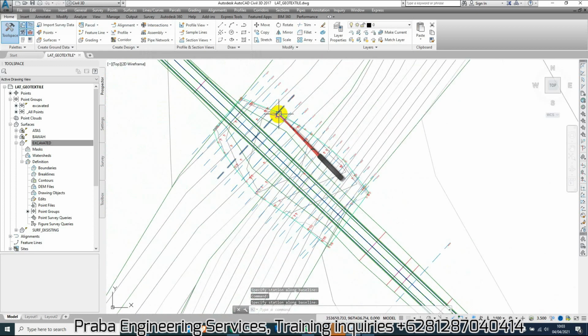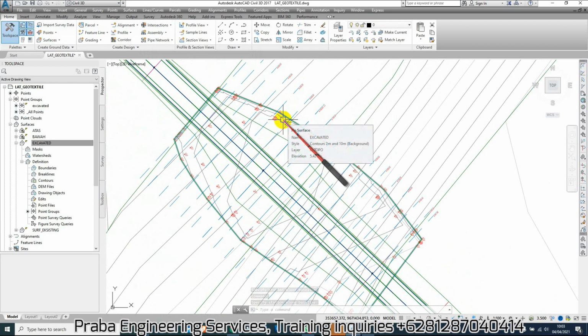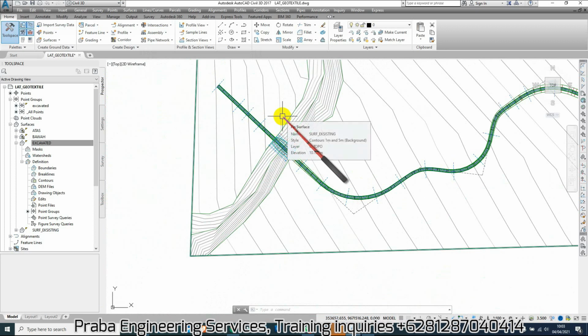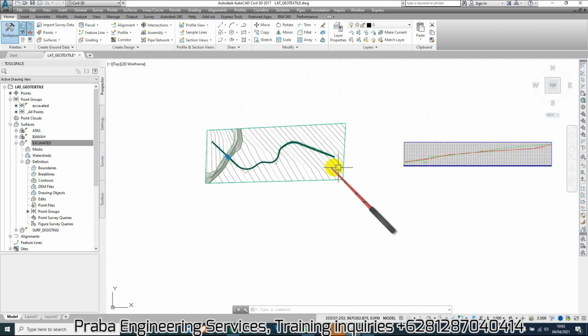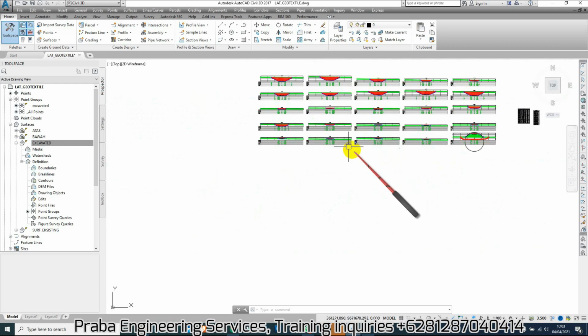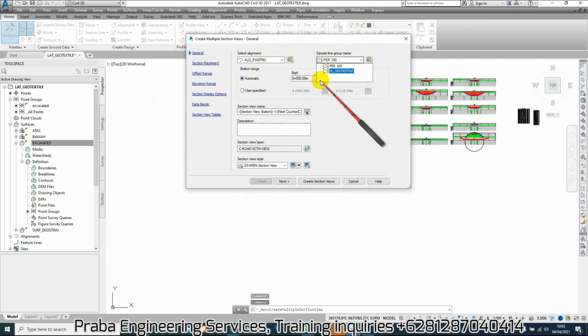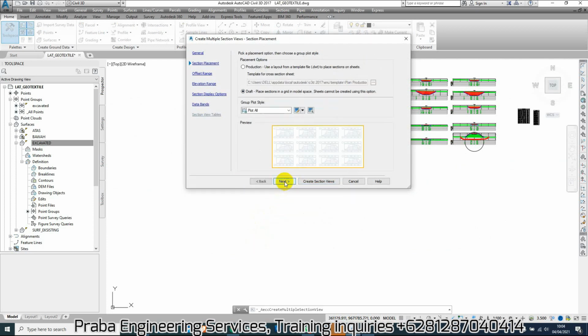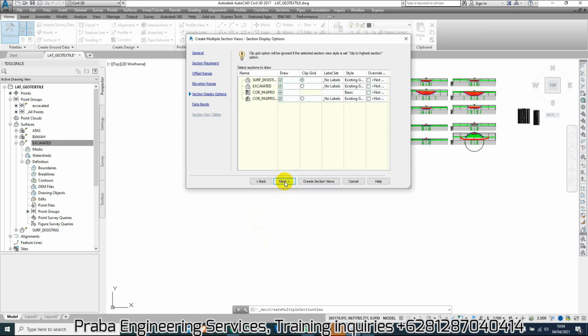Every 5 meters on that location, I already have more detail than the general cross section, because in the general cross section we have only 25 meters. It's very far. Then I need the cross section only for the quantity and so we can get the payment for the progress payment section. Get multiple. Go to the GeoTextile only, and style by the cross view, another sample line.